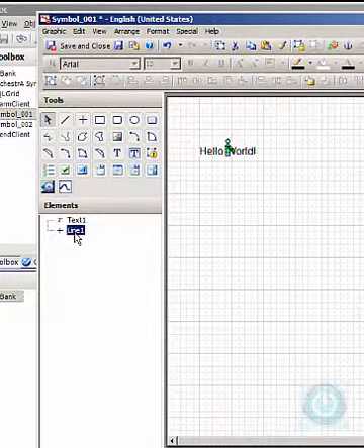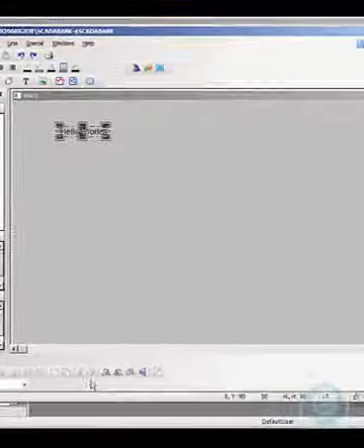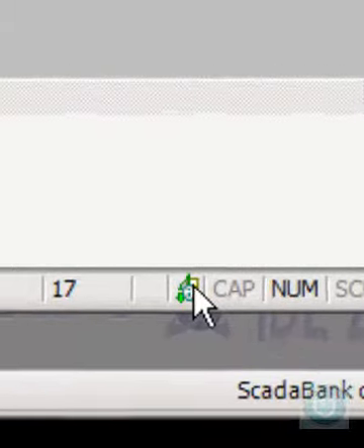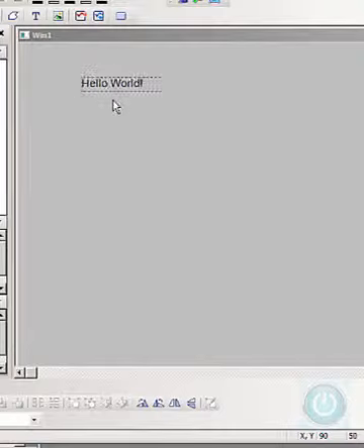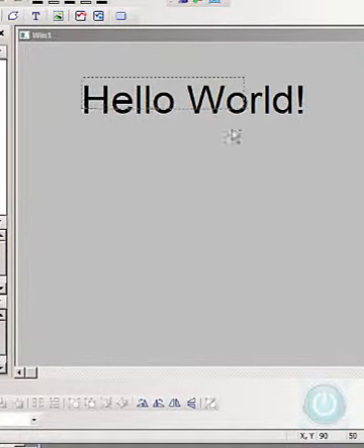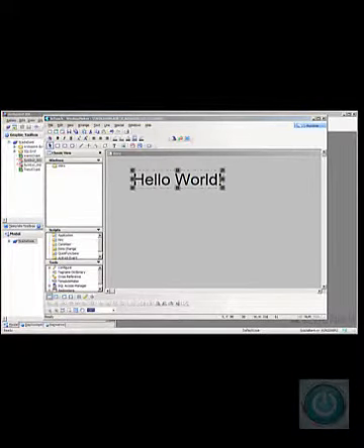And then the last thing I'm going to do is rename it the aspect lock so that anyone opening this graphic in the future will know what that little line is for. Now let's go back into WindowMaker and update that graphic, and finally watch when I resize in the Y direction. The aspect ratio of this graphic is now locked. And the key once again was to have something in the graphic with rotation applied.